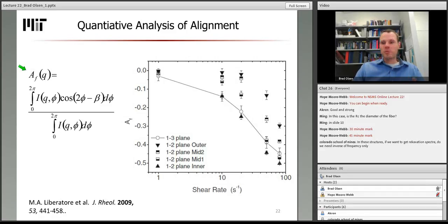So you develop a relaxation model for a structure, and you try to fit that model to the mechanical data and assess the quality of the fit as a method for understanding whether your model is capturing the right relaxation spectrum. So for example, if you hypothesized that you had a reptative relaxation spectrum or a Rouse relaxation spectrum, you could fit this to the mechanical data that you produce and then use that in order to understand whether you have the right relaxation spectrum and potentially to measure a small number of fundamental parameters about your material.